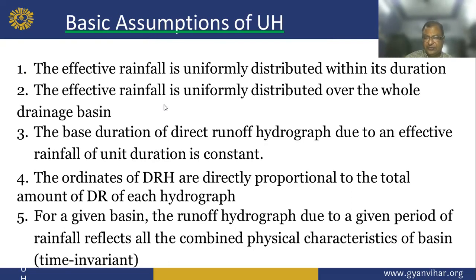Basic assumptions of the unit hydrograph. The effective rainfall is uniformly distributed within the duration, and the effective rainfall is uniformly distributed over the whole drainage basin.